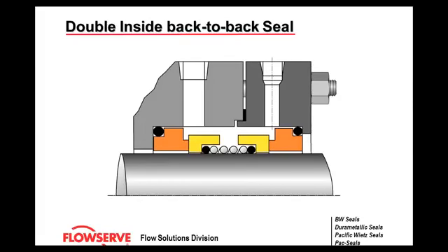Now the rotating element, you'll see, are the two yellow faces, and there's a spring in the middle, and those seals are back-to-back. They're pushing up against the stators, and as the shaft rotates, they run in tandem to seal the system.